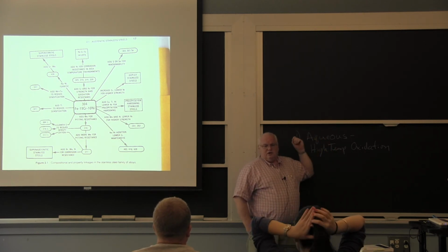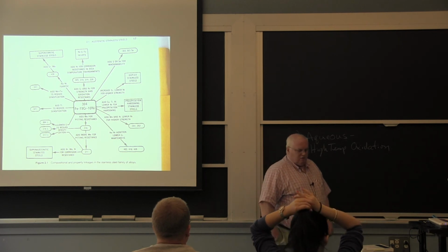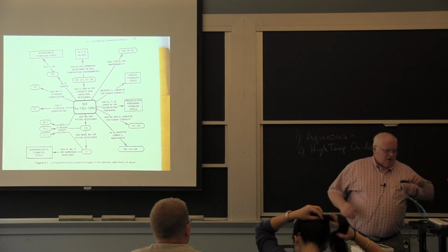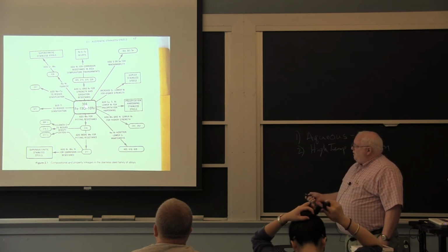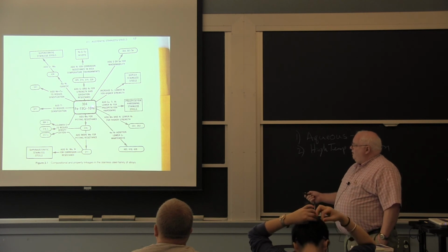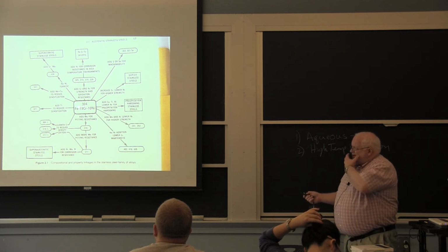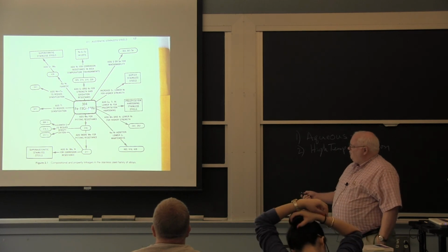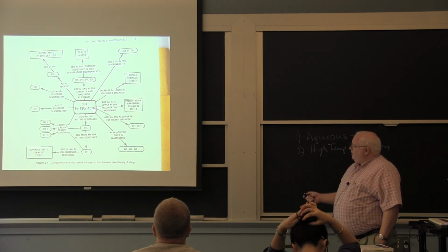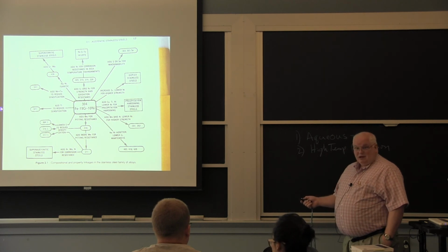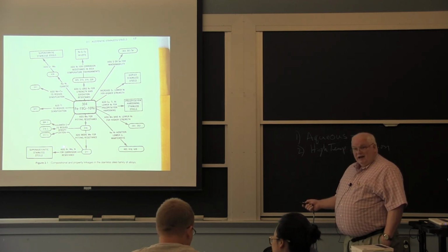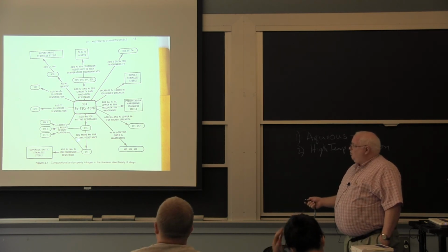Aqueous corrosion resistance, the Achilles heel there for stainless steels is chlorides. And we were talking about how you can add molybdenum, but at a price, something here that might be nowadays $4,000 a ton, maybe. I don't know if I said 2,000 or 4,000. Depends on what the current prices of chrome and nickel are. It's probably around 4,000 today. 10 years ago, it was probably 2,000. But 316 might add $10,000 a ton to that, and 317 might add $20,000 a ton to that. So you're getting pretty pricey. That gives you better chloride resistance.